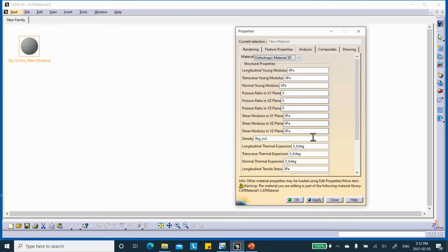Notice that there's 9 numbers that you have to plug in, and I'm going to do that. Let me see. Bear with me for a second, I'm looking at my other screen. Okay, so this one for Young's modulus here in the x direction, I'm going to have 20 GPa, big G, big P, A, so it automatically converts it to Pascal.